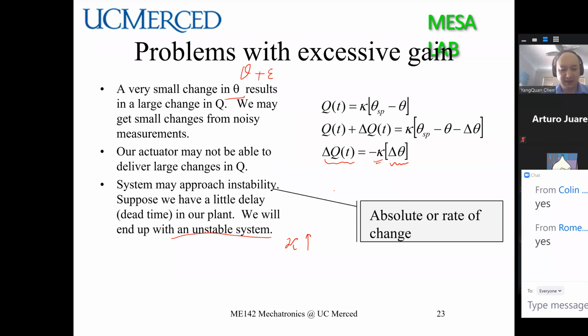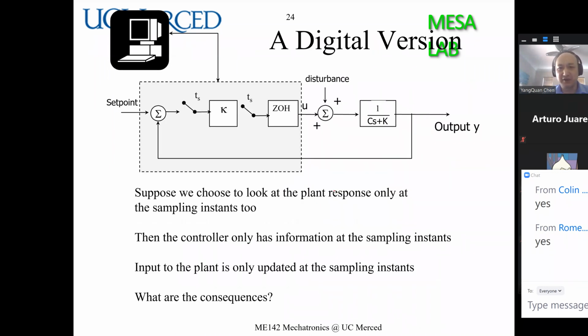That's a different story. We want to now discuss a parallel discrete version of it, a digital version. So again, you have a room temperature control system. So again, this is analog, meaning continuous time signal. But they have a sampler here with a sampling period TS. So this is digital. Okay, this is also digital. Then until you get through the ZOH, here it becomes continuous again.